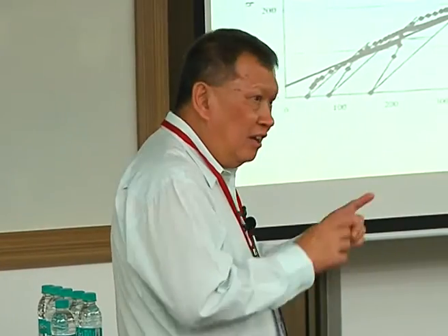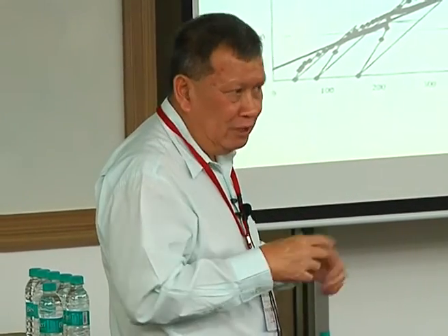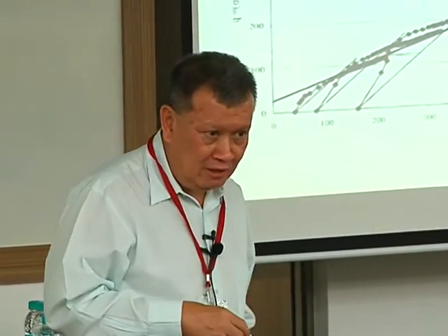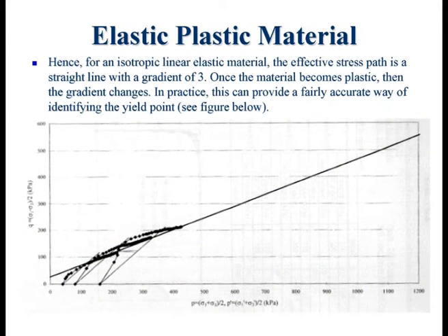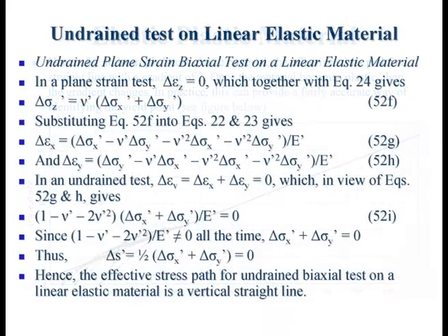And you can then deduce how big the Mohr circle is. Is that all right? The x-axis will tell you the location of the center of the Mohr circle. So you can draw the Mohr circle at failure. Therefore, you can read the stress path like this. You can do a bit of counter-checking on whether the person who drew the failure envelope and gave you the angle of friction has been diligent or not so diligent.